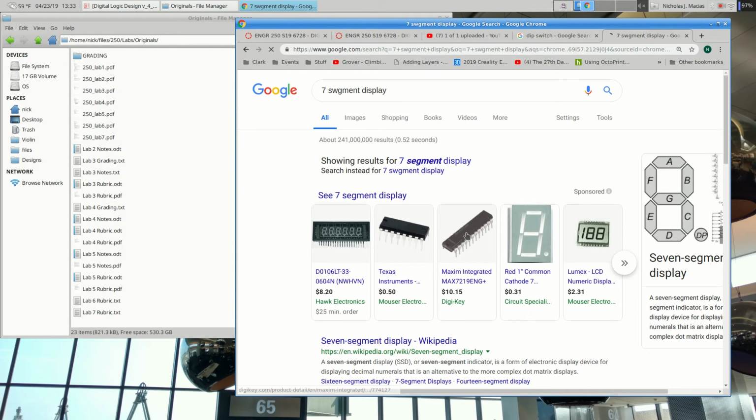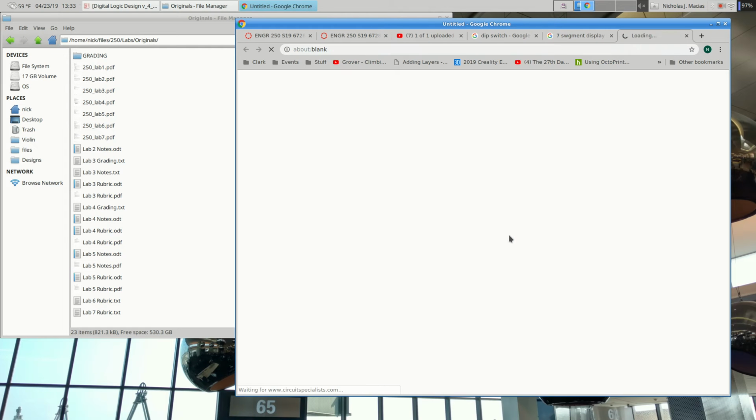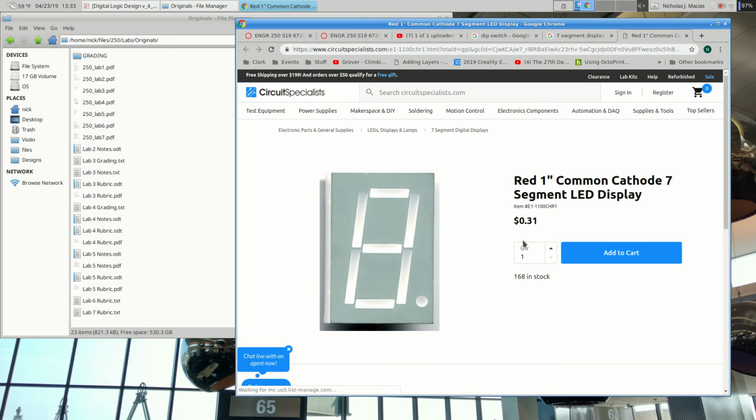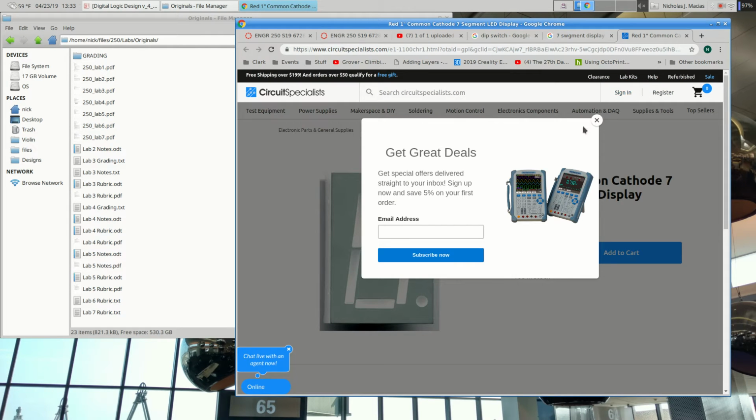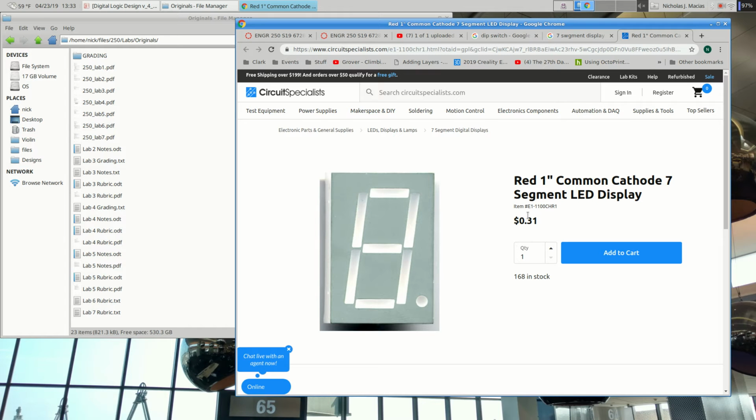We're going to use a 7-segment display. It's going to be this thing that looks like this, and each of those lines, horizontal and vertical, is a little LED. And we can make it light up or we can leave it dark. The idea is by lighting up some of these LED bars, we can make this look like a digit or a letter or just some random symbol.